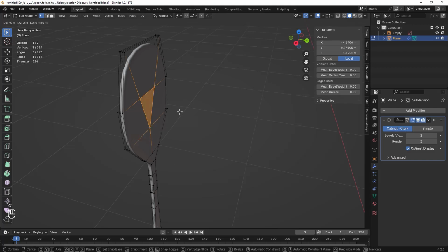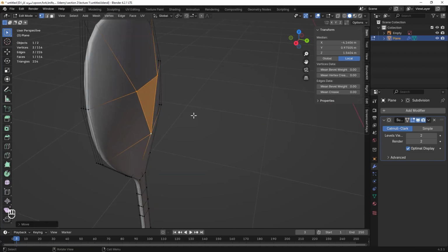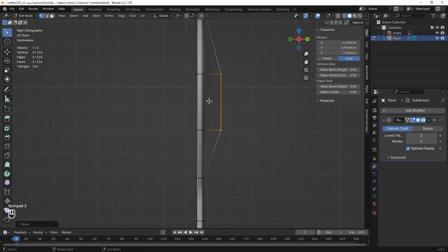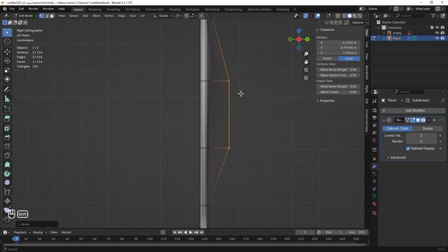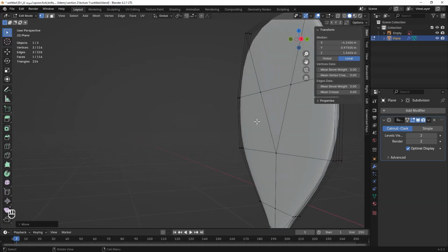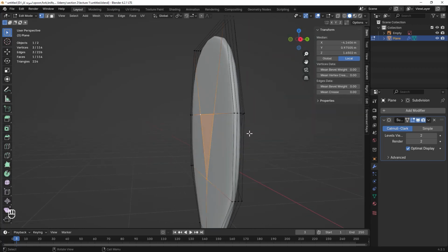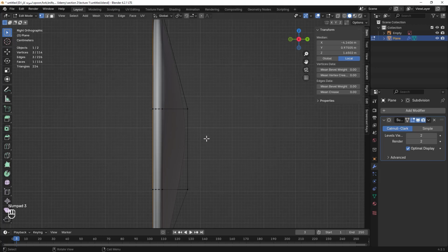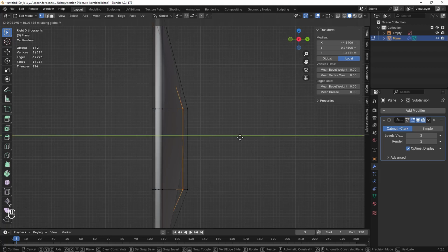And now the actual depth of the spoon: by selecting these vertices and moving them back in the Y direction, in the left or right view, we create a gap in the direction of Y. And again we select the vertices of the spoon with the shift key, three vertices, and move them back in the direction of Y, like the rear faces, but until the faces don't overlap.